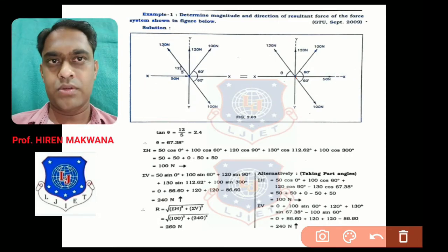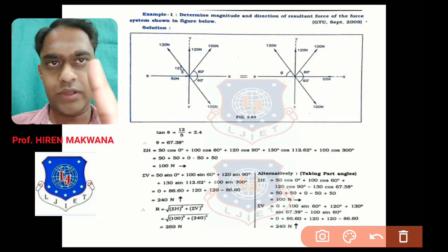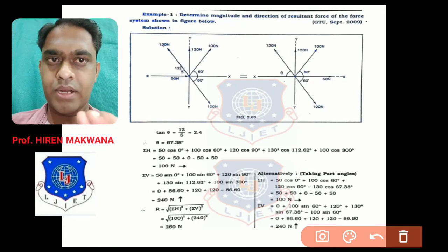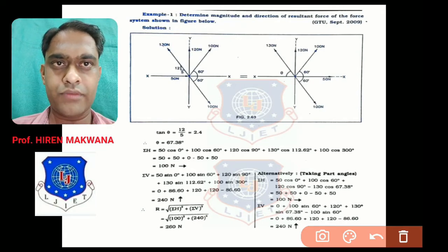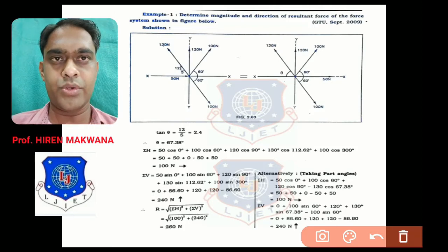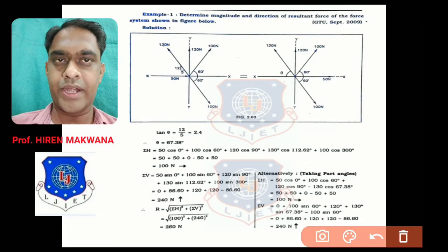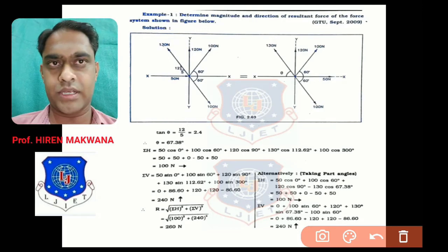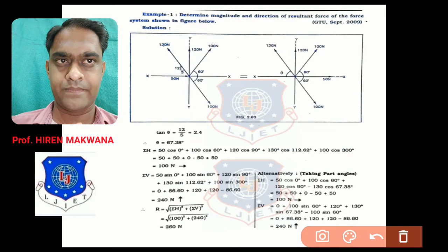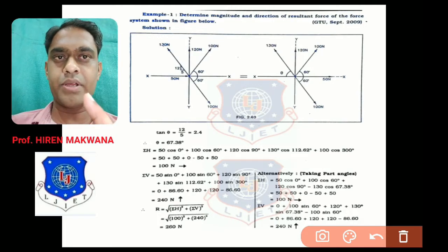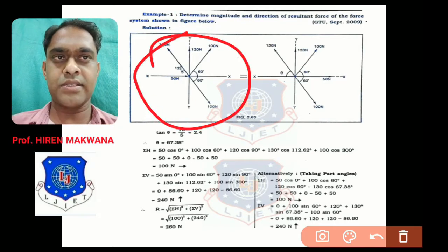Okay. So remember two steps. First step, the angle of all the forces. Remember again, the angle of all the forces must be available to you, but with respect to x-axis only. You have to find all the angles with respect to x-axis only for all the given forces. Second step you have to remember is all the forces in the system must be tensile.